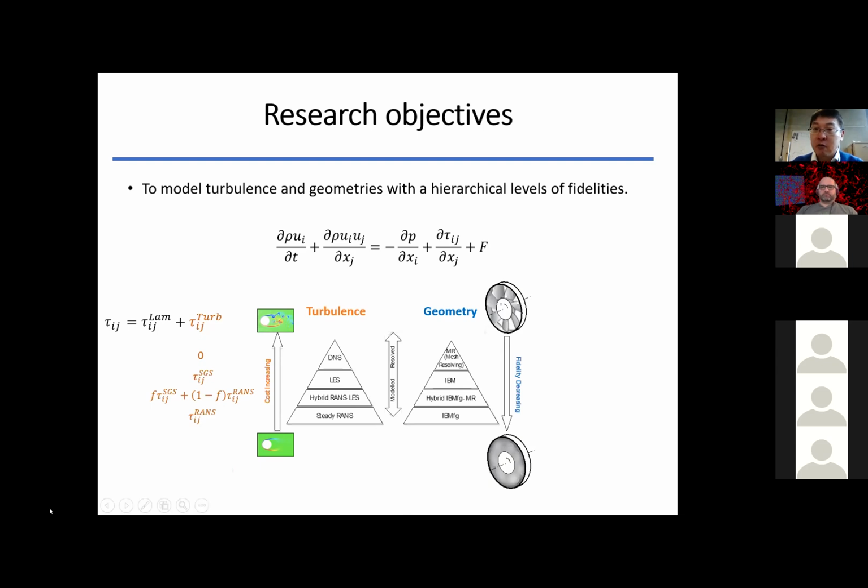And further down to the very bottom, that method is commonly used in turbomachinery, which is the smeared geometry modeling. So we use the average quantities through a turbine blade or the compressor blade, and we only model the flow turnings and the pressure rise or pressure change across the stage to get the right stage characteristics.